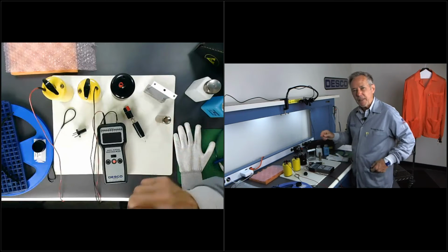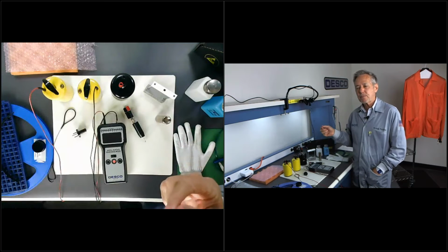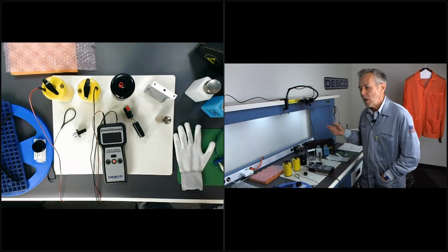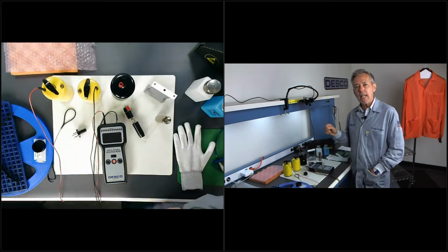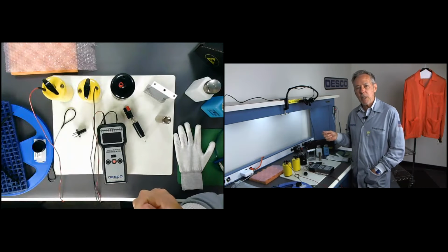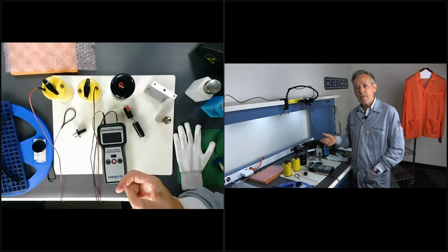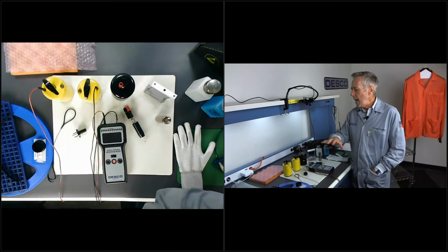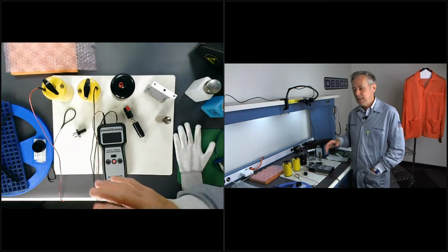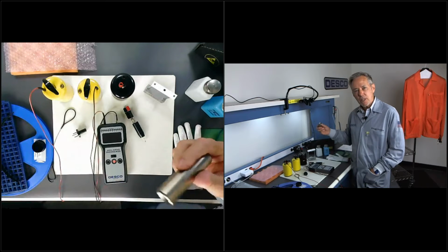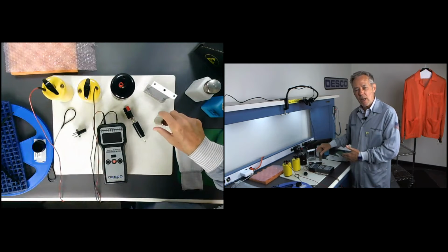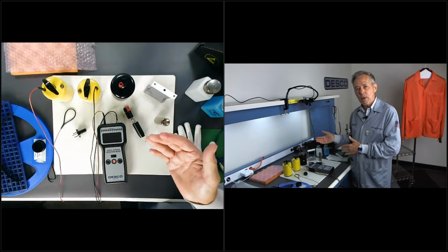Now, I've been talking about the S20.20 standard here, but there's also, for compliance verification, what we call ESD TR53. TR53 is the document that tells you how to use all this test equipment, where to put your probes, what equipment to use, etc. So that's the document that you're going to refer to.